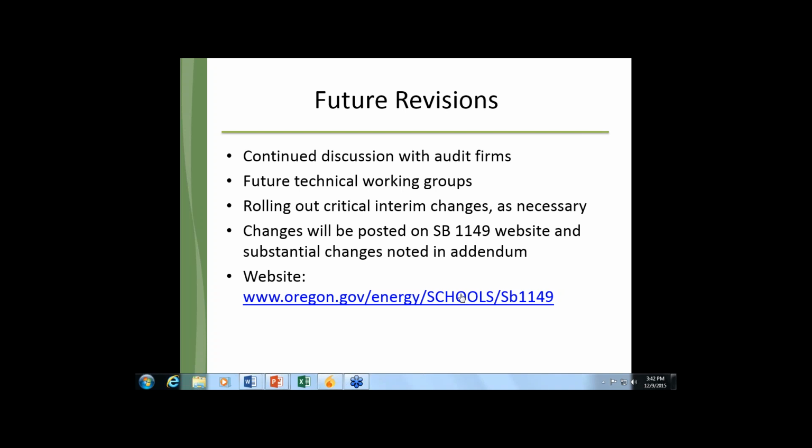There is a catch, however, and we actually came across this. If you find that a building is to be audited for a number of measures, whether it's lighting, HVAC, a handful, not the entirety, and that study is going to be done in the same place at the same time, and by that I mean the same facility more or less at the same time, not necessarily the same day. It could be a couple weeks apart or a week apart, but relatively the same project. That is a single targeted audit. A targeted audit may have one or more measures analyzed. The only difference from a whole building is that those measures are identified beforehand and then analyzed.